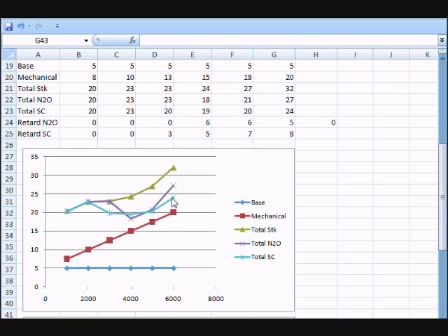power. The thing is here, this is measuring volumetric efficiency, which relates right back to that mixture density that we just talked about. The higher the density, the less timing you need to keep the mixture safe. The lower the density, and the lower the volumetric efficiency, such as our example here on the high RPM, the supercharger isn't as efficient or the exhaust system isn't as efficient as it needs to be. The volumetric efficiency drops a little bit, the mixture is less dense, you can add a little bit more timing to make more power.